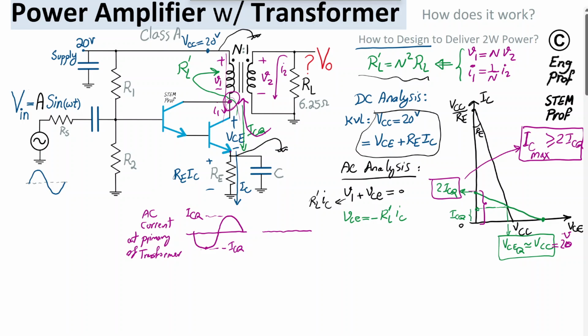So I'm going to show it like this. Here is the VCE of the transistor in AC mode. We have, let's say, the VCQ center point, and then down the total voltage of the collector-emitter, down to, let's say, theoretically 0 but practically 0.2, so basically VCE sat. So VCE saturation of the transistor, which is roughly 0.2 volt, or a bit higher for power transistors.